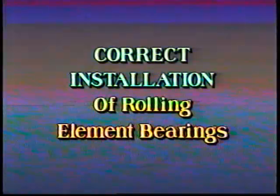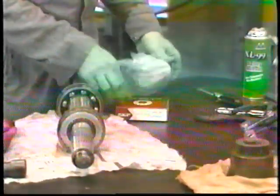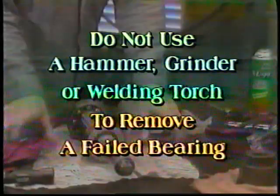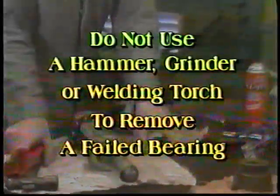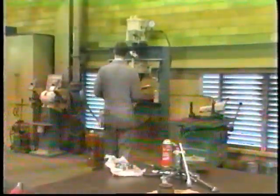Like plain bearings, rolling element bearings must not be distorted during installation. Both rings must be firmly supported by a perfectly round bore and shaft. This means that when you remove a failed bearing for a replacement, you must be careful not to damage the bore or shaft in any way. Removing a failed bearing is often difficult. You may be tempted to break it off with a hammer, grind it off, or even use a welding torch to cut it off. These methods are dangerous and will usually damage the shaft or bore. The best practice when removing a failed bearing is to use a puller or a press adapter.